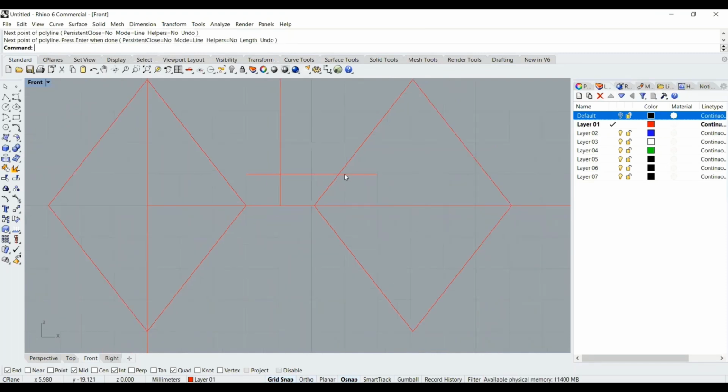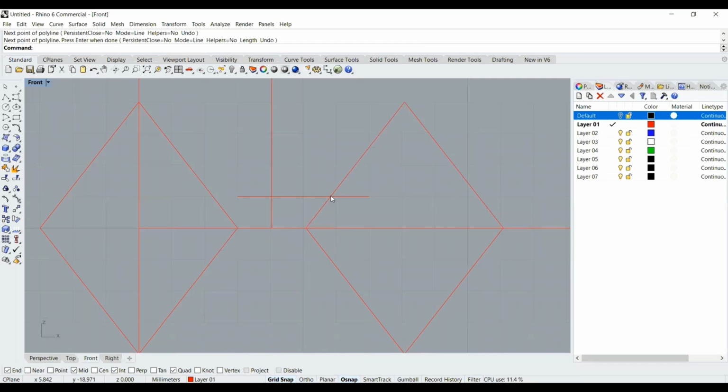And now I just want to know the distance between here and here, so that here at the top my triangle has also the same distance, and it looks like, you know, you've cut and left a bit of wire that is the same width from the beginning to the end. So I'm just going to analyze distance and measure here, and it is 1.789 millimeters.